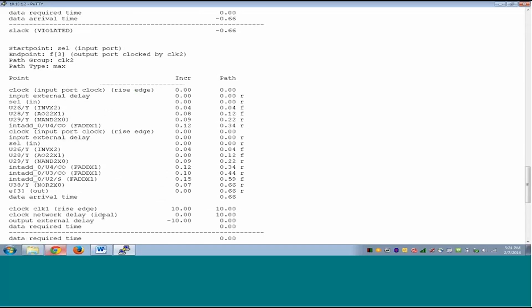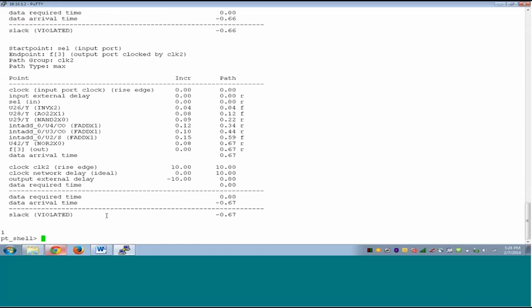Obviously it is not apparent in such a small test case, but when you are working on a big design and a big chip, this functionality is very useful. We make use of it all the time. You can even save the session and point it to some other engineer who can load the session. On a big chip, at one time on full chip STA, there is more than one person working. You can save a session, give it to another engineer, and he can restore that and do analysis himself, right?